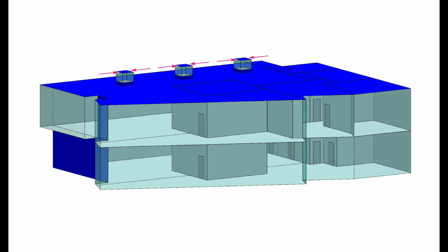the dominant wind. As location 1 mainly favored the first floor, location 2 was chosen at the core in order to deliver more air to the ground floor, assuming the doors are kept open. Scenario 3 has 2 wind catchers having openings facing the dominant wind. Scenario 4 has 2 wind catchers with openings at the opposite ends, one of them at the dominant wind direction. Scenario 5 is quite unique, where it tries to dedicate one wind catcher entirely for air entering the core and the second for air exhaust.